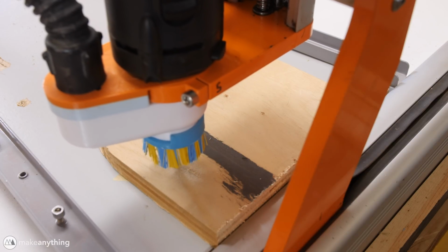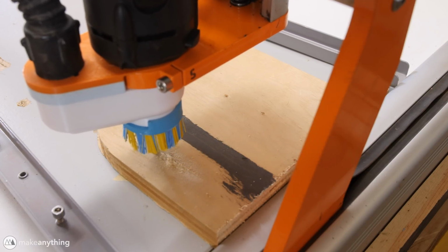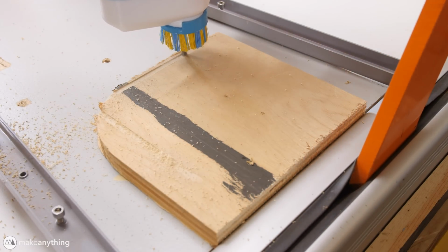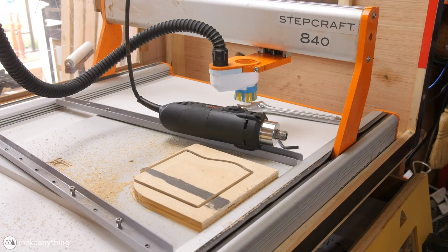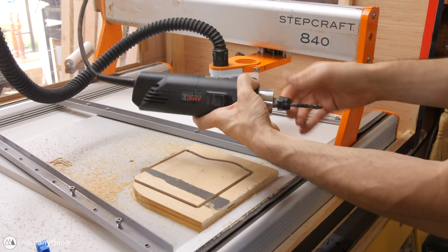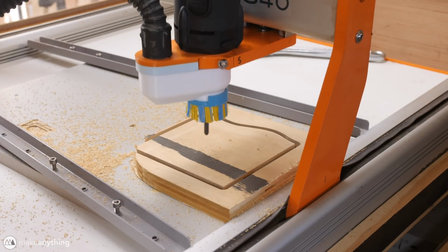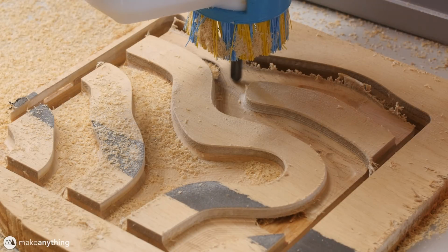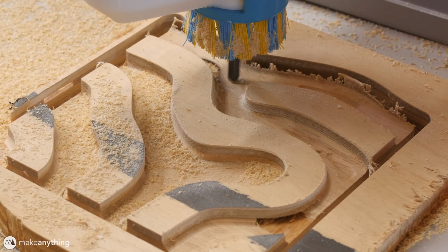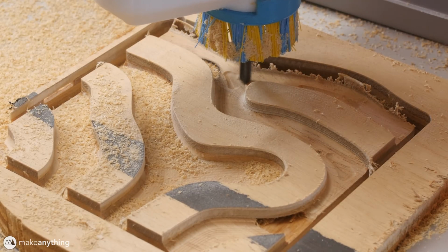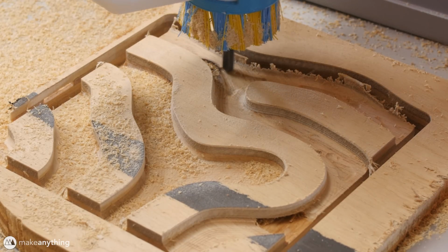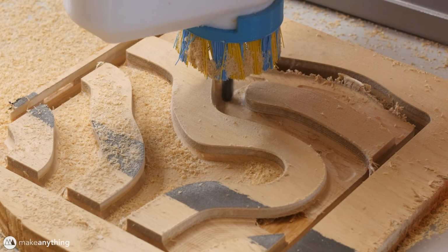So this cut that you're seeing is the first of two processes that are combined to create the final piece. First, I did this outline cut with a flat end mill, and then I'll swap it out with this rounded end mill so that I can do the pattern. And that's simply a matter of preference. I want the inner edges that are being cut out to be rounded, and that's exactly what this end mill will do. So here it is, cutting out the pattern 1 millimeter at a time. So it's really just like the exact opposite of a 3D printer. Instead of building up one layer at a time, it cuts away one layer at a time.